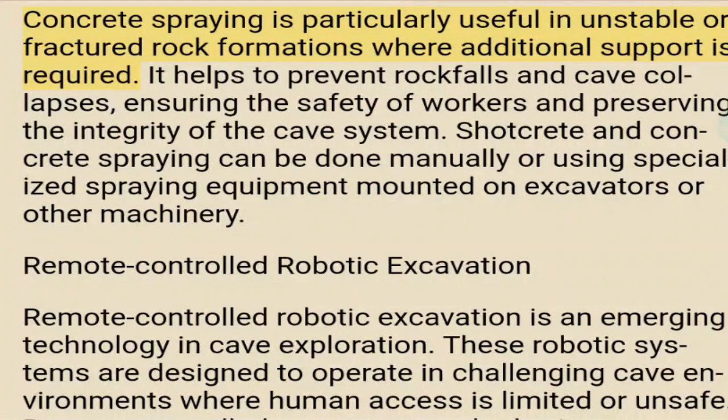Concrete spraying is particularly useful in unstable or fractured rock formations where additional support is required. It helps to prevent rockfalls and cave collapses, ensuring the safety of workers and preserving the integrity of the cave system. Shotcrete and concrete spraying can be done manually or using specialized spraying equipment mounted on excavators or other machinery.